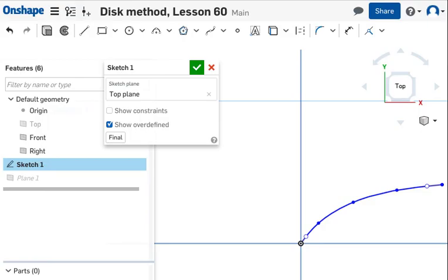Look, here's a similar curve. It's in Onshape, the CAD program that in the first quarter I encourage you to learn a little bit about. And what we can do here is just kind of finish this out. We have to have a face, an area under that curve. It's a little bit different method, but just think about that solid of revolution there. So I can use this line tool and go from here and go straight down. Click. I made that segment, then go from here to the origin there. And make a line there. Hit escape. Now I have that surface there.